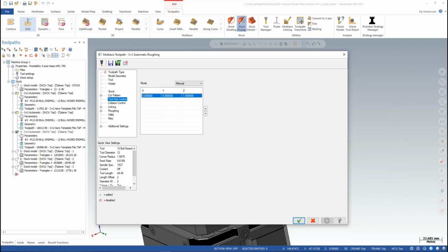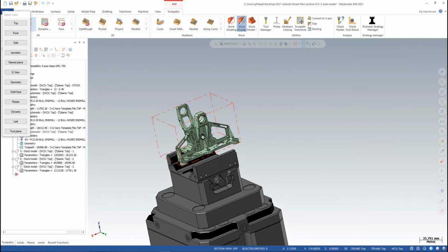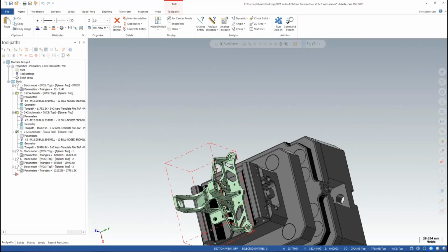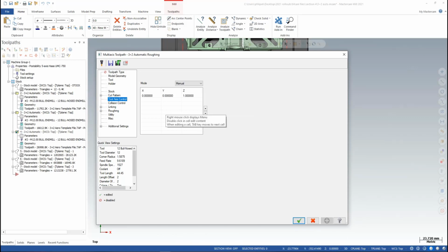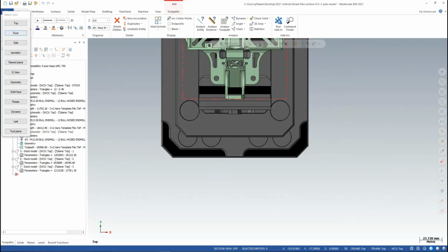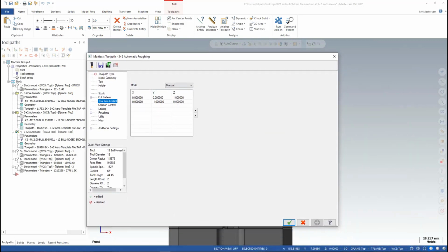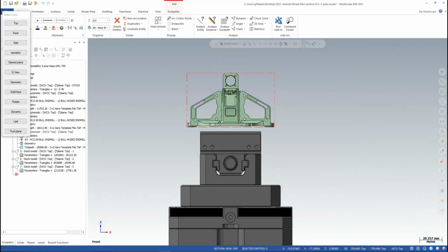And I'm going to leave the first one in there. Let's remove it. So I'm going to select the tool plane, and I'm going to say, give me a plane at the top. So I'm just going to say top. Gives me a plane there. I'm going to right-click, select tool plane, and I say go to the front. Puts a tool plane on the front of the part for me automatically. It's building these as we go.